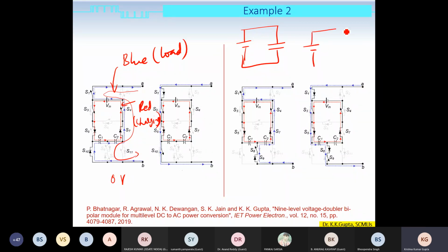What I'm doing here is using two capacitors, which are in parallel with the source. This is an approach where the ESRs of the capacitors will be playing a role in limiting the charging current. So this approach is beneficial in limiting those currents.